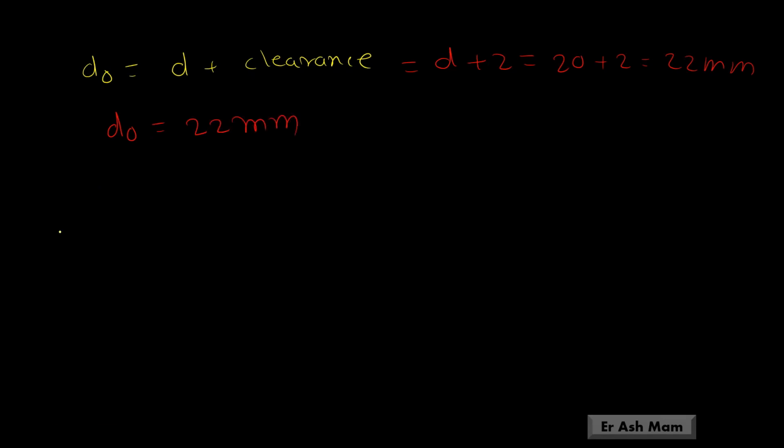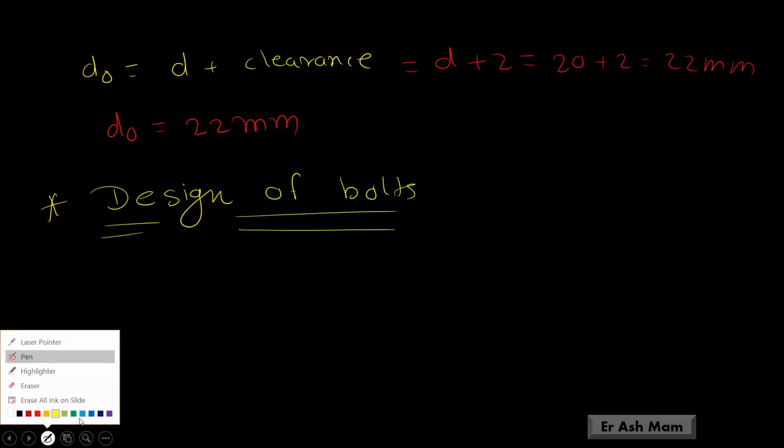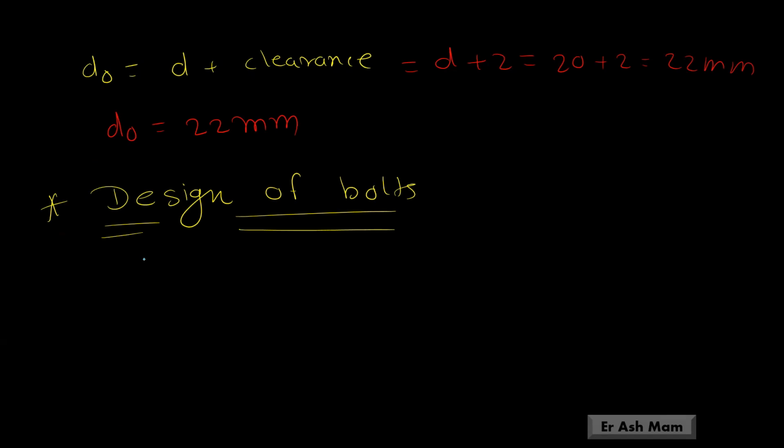Next, first step, design of bolts. In design of bolts, grades are not given. Therefore, we can assume grade, using M20 bolts of grade 4.6.